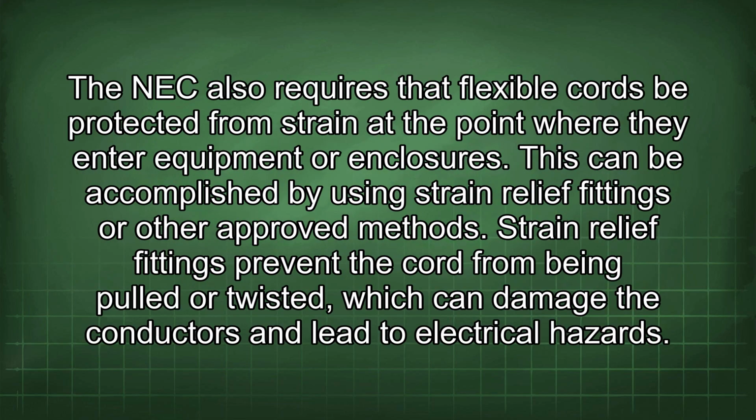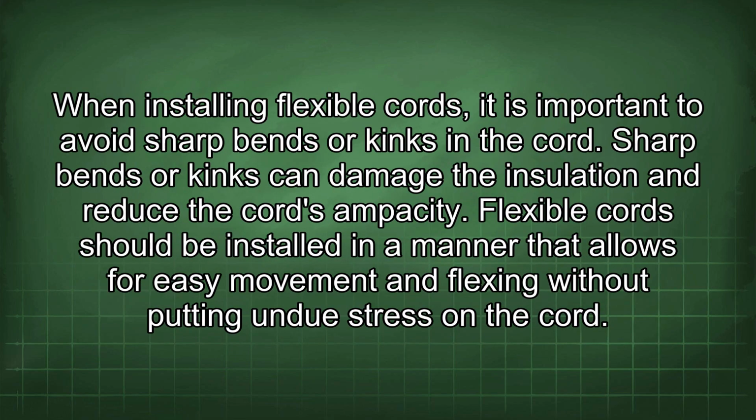The NEC also requires that flexible cords be protected from strain at the point where they enter equipment or enclosures. This can be accomplished by using strain relief fittings or other approved methods. Strain relief fittings prevent the cord from being pulled or twisted, which can damage the conductors and lead to electrical hazards. When installing flexible cords, it is important to avoid sharp bends or kinks in the cord.